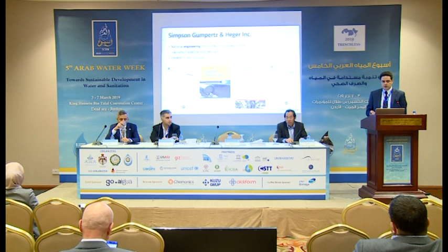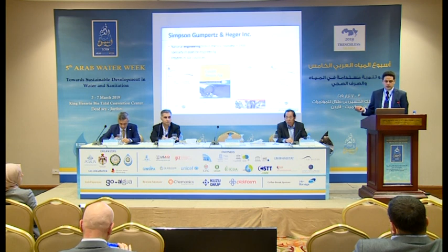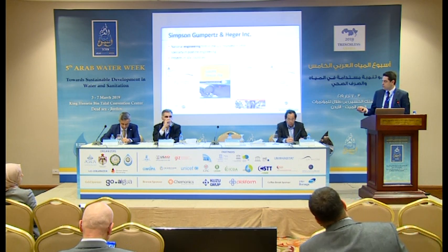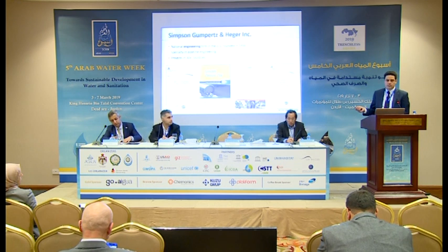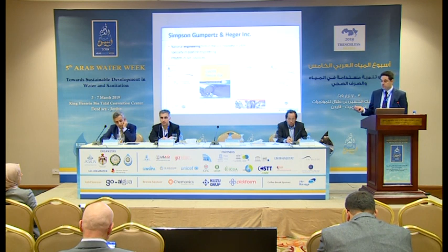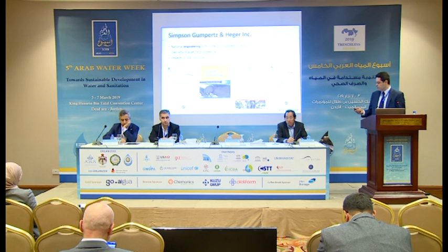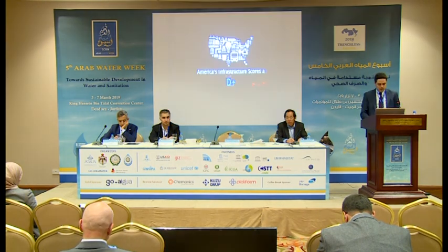Some of the standards that we significantly contributed to are shown on this slide, ranging from the design of pre-stressed concrete pipe, which is AWWA standard C304, the manual that goes into more details of that design approach, condition assessment best practices manual, and most recently, we assisted and led the development of the CFRP, carbon fiber reinforced polymer renewal of concrete pressure pipe, which just came out a couple of weeks ago as a new standard, AWWA C305.